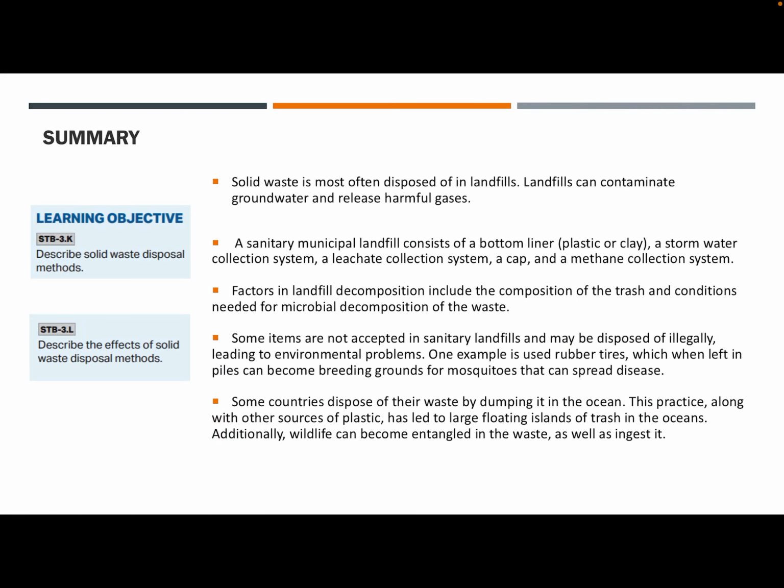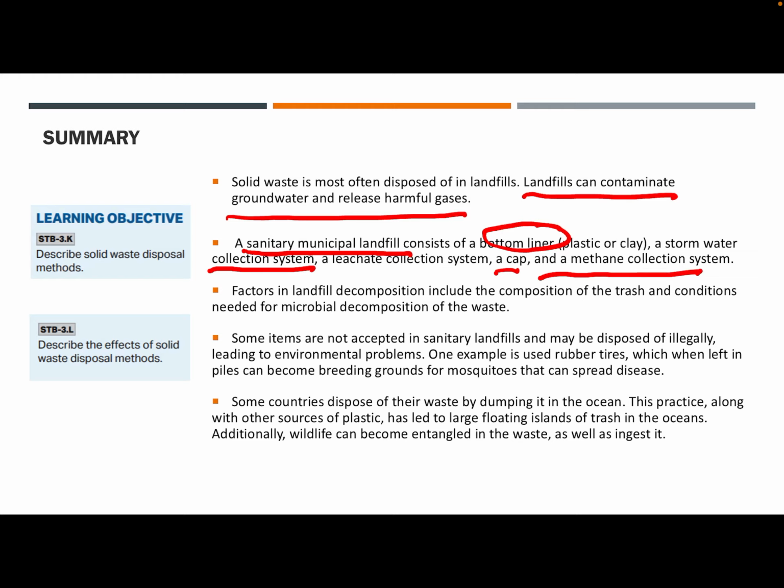So to summarize, there was a lot of information in this, but solid waste is most often disposed of in landfills. Problems with landfills is they can contaminate groundwater and release harmful gases. A sanitary municipal landfill has to have a bottom liner, plastic and/or clay, stormwater collection systems to prevent that leachate, and a cap, which is also made of plastic and clay, and then a methane collection system.